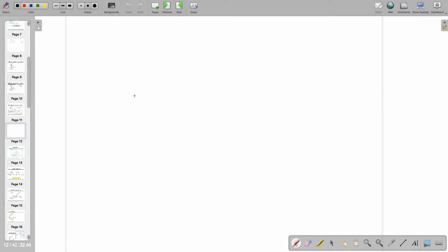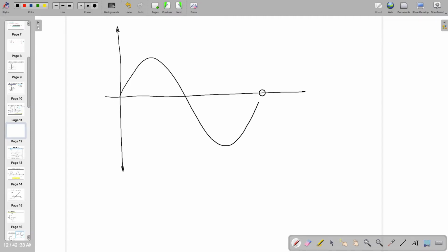So if you look at this, if this is your input, amplitude with respect to time, so if this might be till 5 and this might be till minus 5, right? Then it will wait for 0.8 volt or the VBE, and then it will track the output. But in this circuit, does it go below this 0 volt or not?